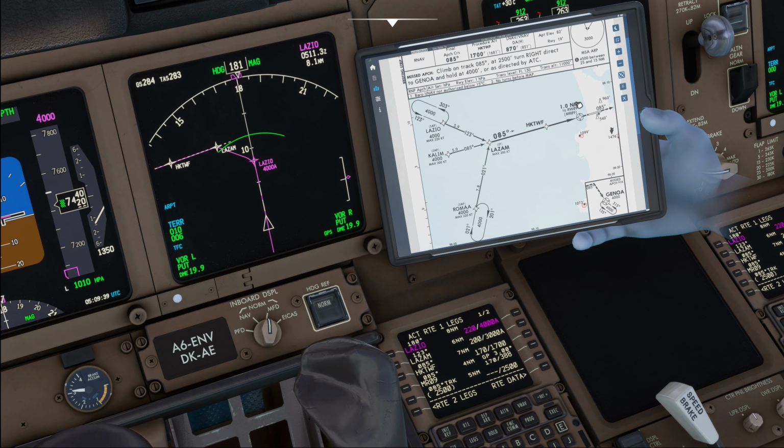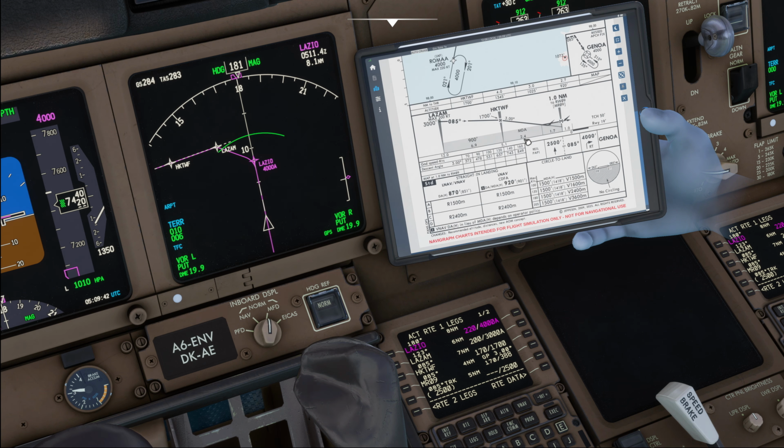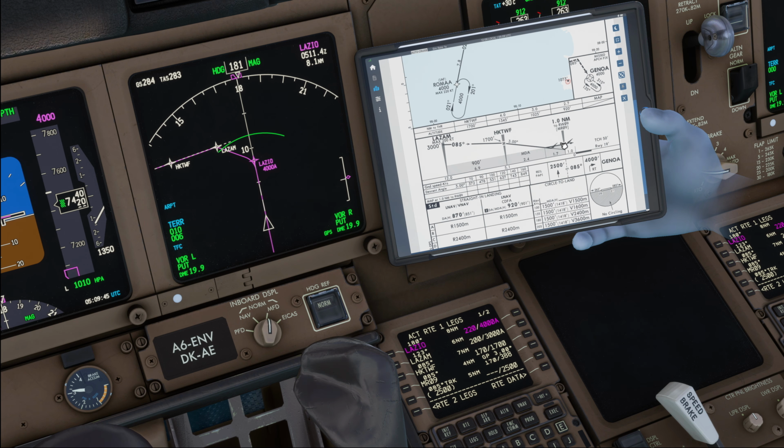So finally then, we've got our missed approach fix 1 mile from the runway, and that one is, of course, located at an altitude that's a little bit further down from what we normally know, and we might not always have an altitude associated with that available in the database or on the chart. For that reason, what we can do is just to apply a bit of common logic. So we can see over here we've got 1 nautical mile between the missed approach point and the runway threshold. The threshold is at 19 feet and the threshold crossing height is 50 feet. So basically what we get is that right at the runway we should have an altitude of 69 feet.